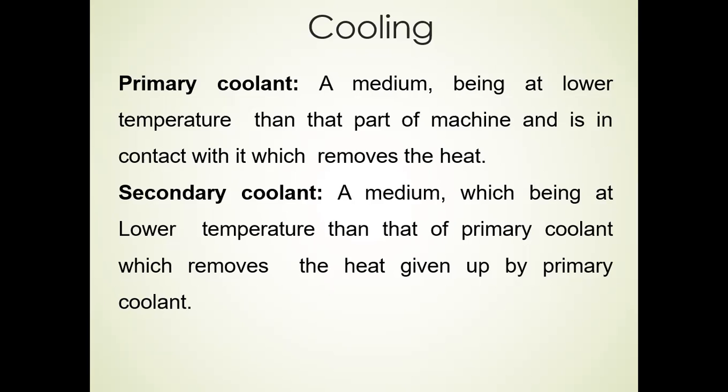That is, the purpose of standards on degree of protection and cooling system is to ensure good understanding between the manufacturers and users of electrical equipment with respect to related aspects. The heat due to losses in the machine is imparted first to primary coolant by raising its temperature. The heated primary coolant may be replaced by a new coolant at a lower temperature or may be cooled by secondary coolant in some form of heat exchanger.